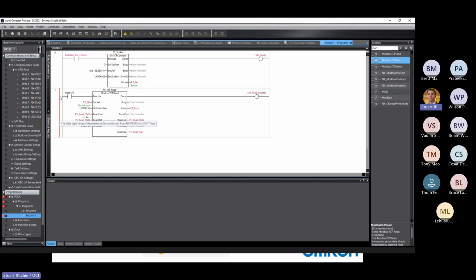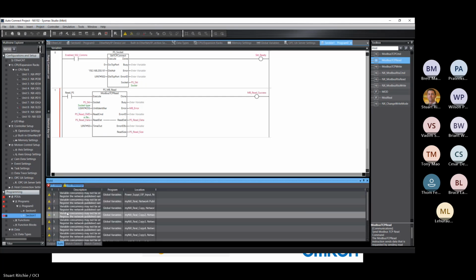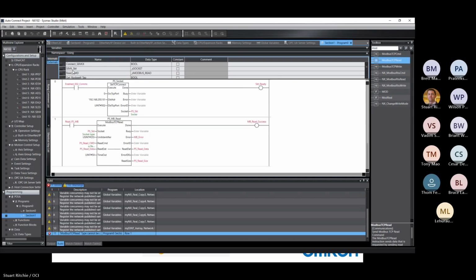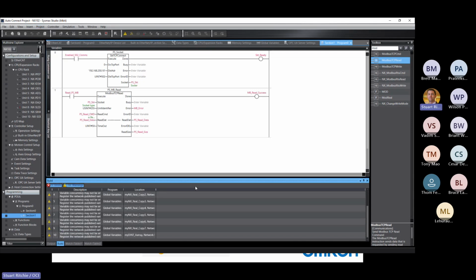And you see a red line next to the rung. This is a uSint, and I specified it as a uInt. So I'll make that a uSint. That should clear it. Almost. Okay. So warnings are okay, errors are not. We've got 0 errors, so we can transfer to the PLC.